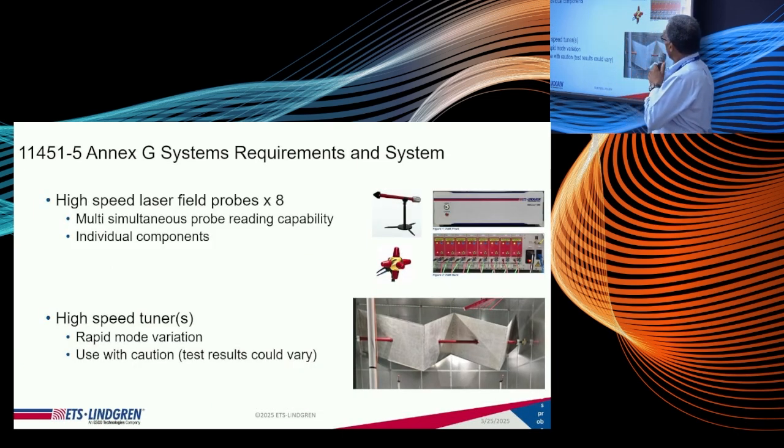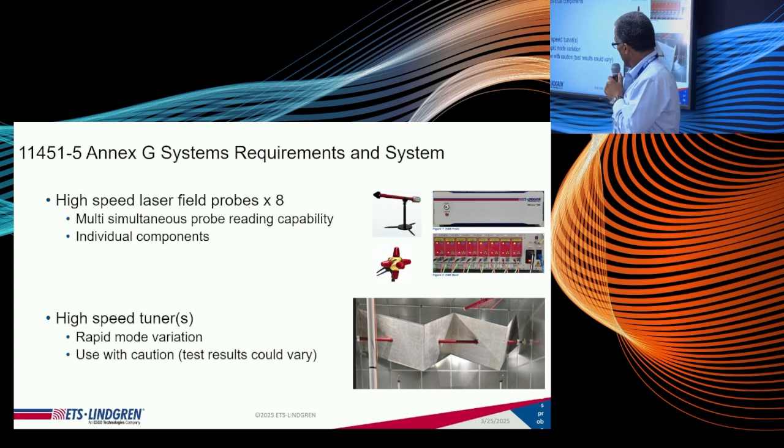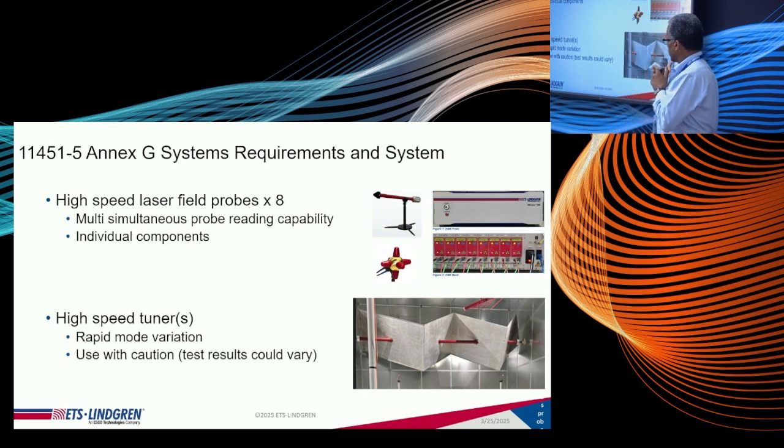The big change here is the use of the 8 probes simultaneously, all sampling on the fly during the course of the measurement. And then RF tuners, various speeds. The standard now supports what's called high-speed stirring so that you can really stir those modes very, very quickly and take advantage of probes if they're very high-speed probes.